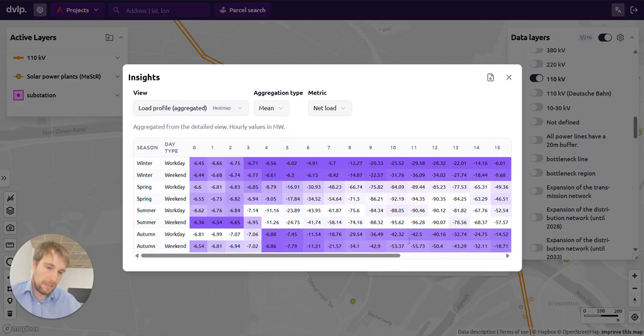And if I would now connect another generation asset, as an example, in my case the battery storage unit, I would very likely have to count in a flexible connection agreement and potentially a loss of operation freedom during these peak hours here. So that's something that I can nicely anticipate by viewing this data here.